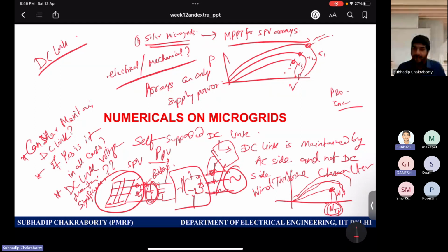It seems mechanical. It's both mechanical because of the turbine characteristics, and since you want to match it using the electrical characteristics of the generator, it is electrical. Yes, it is, sir. Both also. So it's electromechanical MPPT that you do in wind. So both electrical and mechanical together we try to do MPPT. This is a completely different essence compared to that of solar.